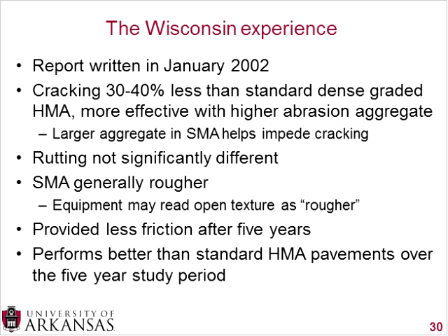After 5 years, they found approximately 30 to 40% less cracking than standard dense graded HMA. And there was even less cracking when you had higher abrasion aggregate values, because the larger, stronger, more durable aggregates helped impede that cracking.